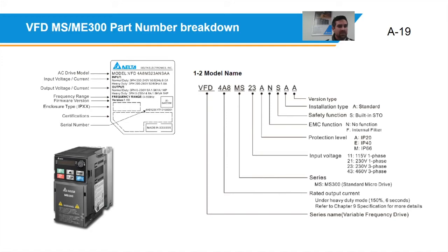So yes, C2000, as far as I know, 100% is the only drive that can be used as a master. But it doesn't have the functionality of the PLC link like you enjoy inside of the PLC software. It's more of a manual mod read, mod write instruction targeting particular registers. So JJ, to answer your question, ultimately, there's no development that I know of including PLC link as the driver, let's call it, inside of the VFD PLC software. But the C2000 can do mod read, mod write.